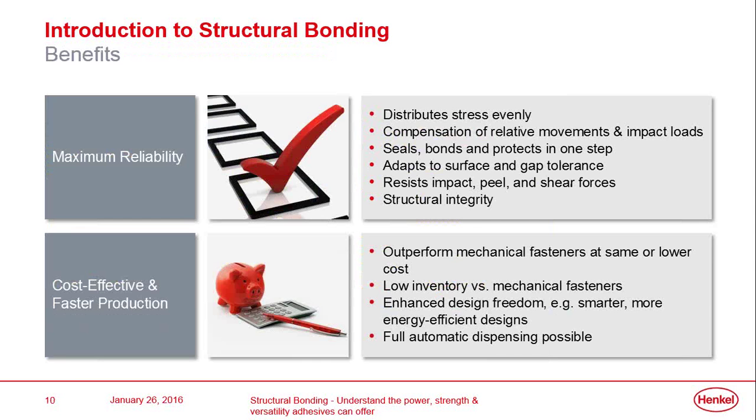So, if we look at the benefits, we're looking at even stress distribution, we're looking at compensation of relative movements, we're able to bond and seal in one go, and we can deal with lots of different tolerances as well. Different materials have different surface finishes. Because we're applying adhesive as a liquid, and we can choose how well that liquid flows or stays in place, then we can join all sorts of materials with different gaps, and you can see that we can resist impact, peel and shear forces